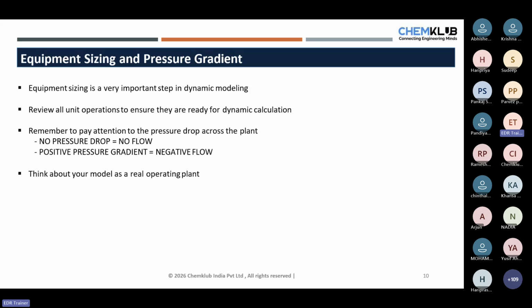So a very important parameter here is to understand that you have to give an equipment sizing also, and it has to be very correct. Otherwise, whatever dynamic analysis you do has got no meaning. So that is why sometimes the dynamic simulations are done at a later stage where you have already frozen the plot area, the piping routing, etc., and you have got the final volumes of the equipment, and then you can put all those in to get a meaningful result out of it.